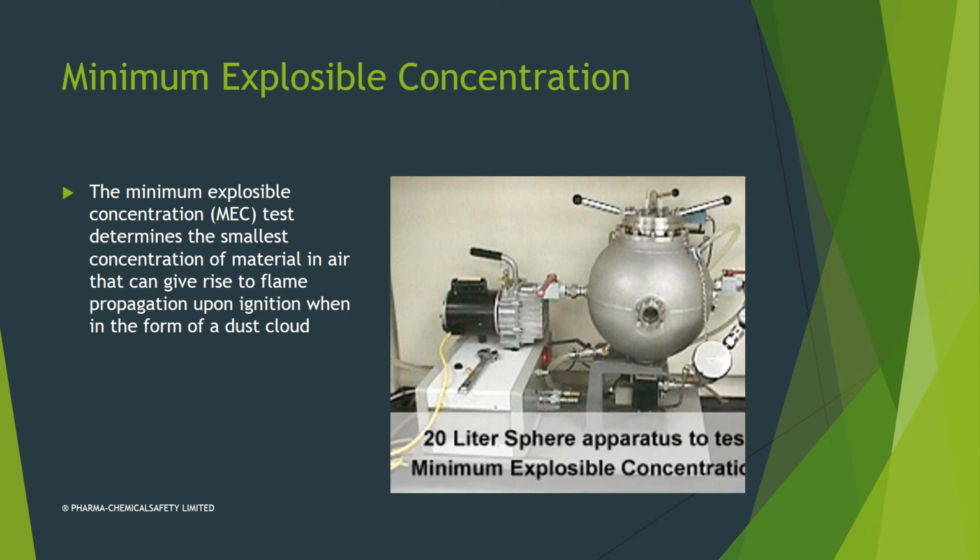So another parameter that is so critical is the minimum explosive concentration. It's the smallest concentration of the material in the air that can give rise to a flame, or can produce a deflagration up to the ignition when in the form of a dust cloud. And that's one of the critical parameters, especially in the pharmaceutical and chemical industry, when you empty these powders into the mixing tank, or when you generate dust due to your operation.